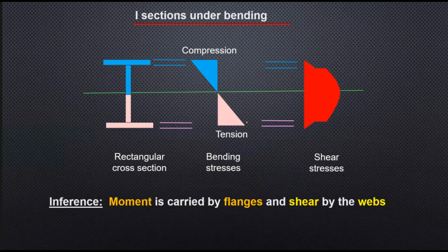This is the most popular example. I always love to explain that we have a rule in the design of plate girders that the moment is carried by the flanges and the shear is carried by the web. Correct. Why do we say that? Right. Now I have the area of the flange, which is really maximum, and I have, let's say, this Fy, the maximum.